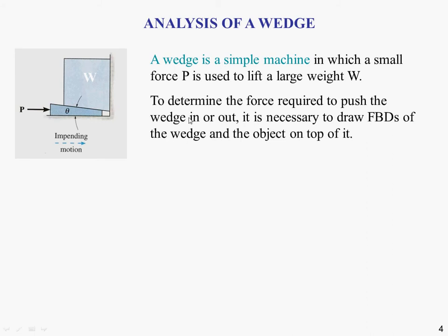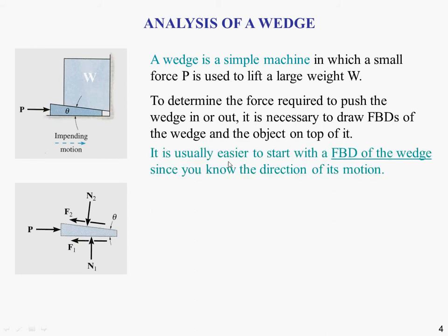To determine the force required to push the wedge in or out, as with most, if not all, engineering mechanics problems, we need to draw some free body diagrams. Okay, so we've drawn here the free body diagram of the wedge, and it's usually easier to start with a free body diagram of the wedge, because usually we'll know the direction of its impending motion. Okay, so here we're pushing the wedge in, so we know that the impending motion is to the right.